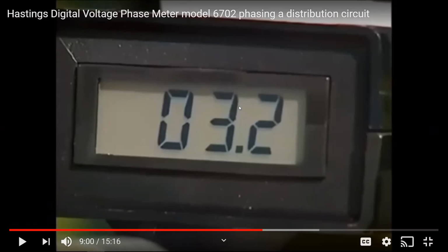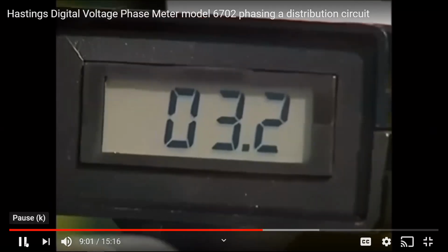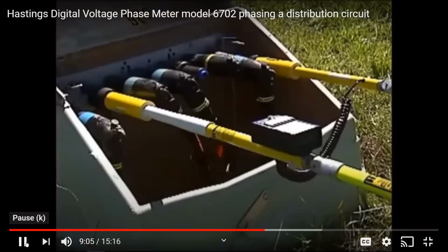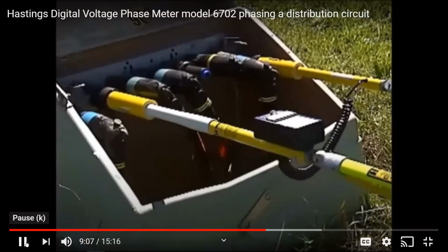The question on the test is going to be, I put my phasing sticks to test my conductor, and the voltage always stays high. What kind of fault is on the conductor? Bolted fault. That's as short as it gets. It's a bolted fault. So we've got a bad underground situation here.